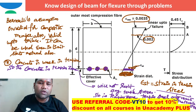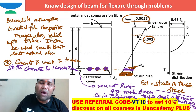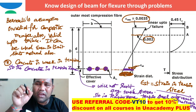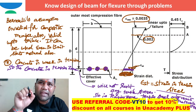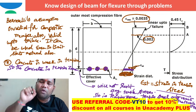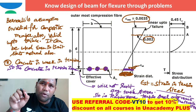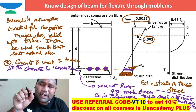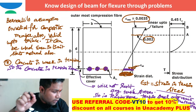Now the question is, some people will also ask me, "Sir, really, can the concrete not resist even very small tensile stresses?" Concrete can resist very small tensile stresses, which is very negligible. If you are very particular and interested to learn about the maximum value of tensile stress the concrete can resist in tension, you need to know about the modulus of rupture, right?